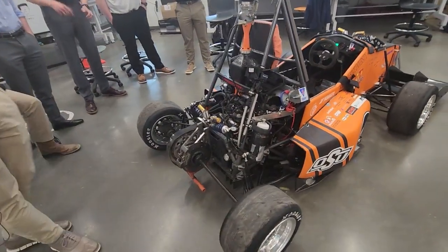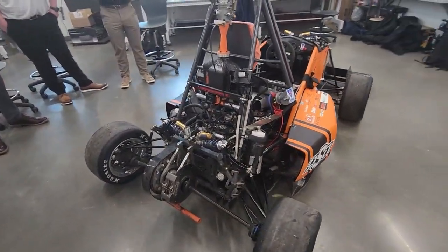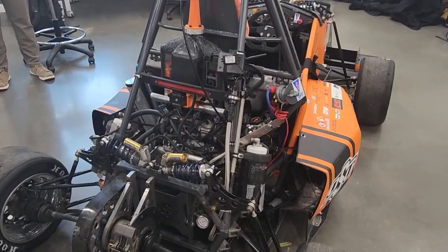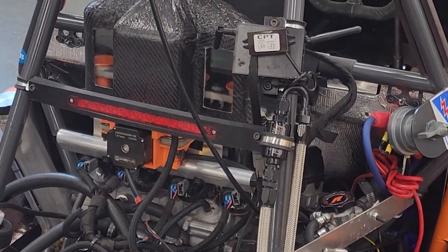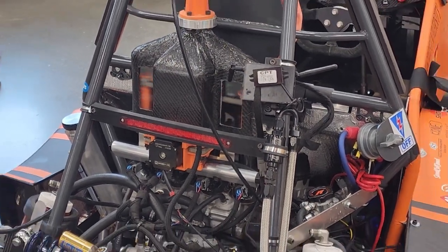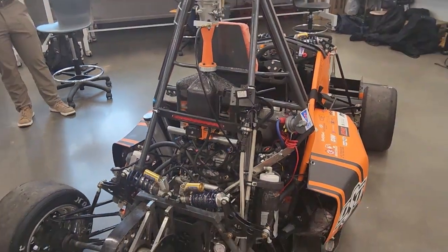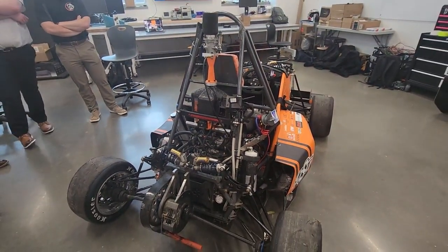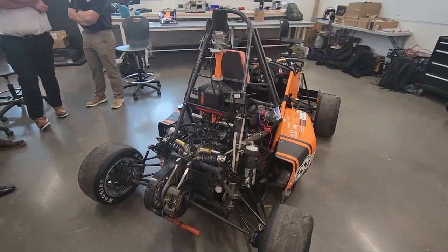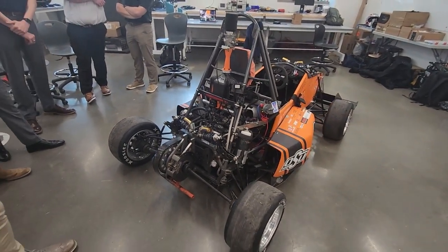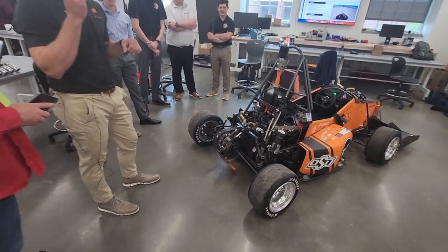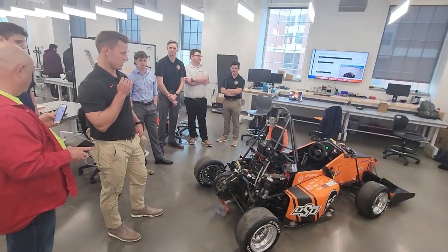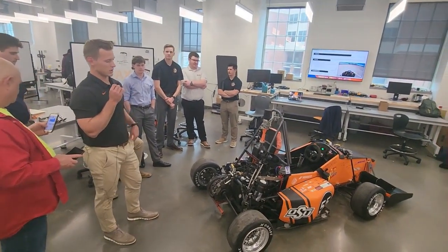But basically the premise of this project is to take advantage of what's called the Helmholtz effect. And so basically whenever the valve closes that allows air to enter the cylinder heads there, when the air bounces off that valve and bounces up, it causes a pressure wave to take place. And so we're trying to optimize the timing of that pressure wave so that when it hits the valve again, it's at full force, full velocity, coming into that cylinder head and hopefully broadening our torque curve.